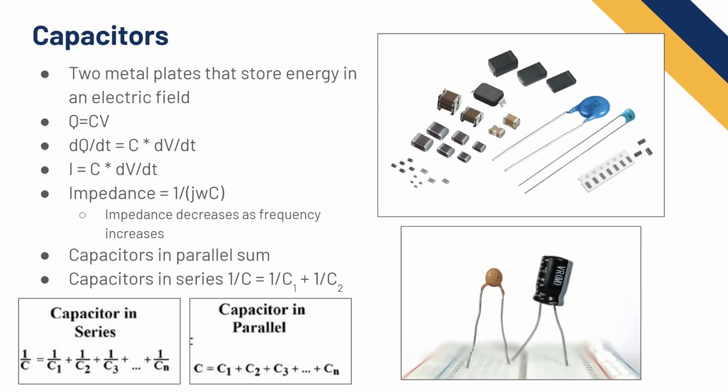Although we try to stay away from tantalum capacitors because they're made from conflict materials. So yeah, we try not to support that. And then you have some through-hole capacitors like that. Sometimes through-hole capacitors look like these blue ones on the top. Sometimes they look like these beige ones on the bottom. Those are ceramic through-holes. But then sometimes they look like this black cylinder over here, and that's an electrolytic capacitor.